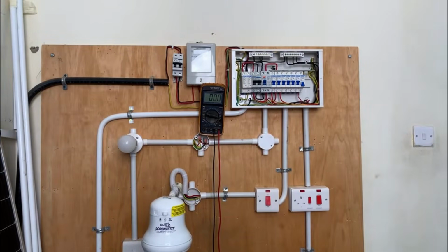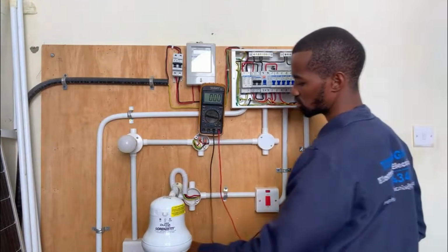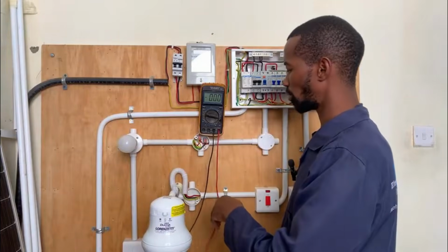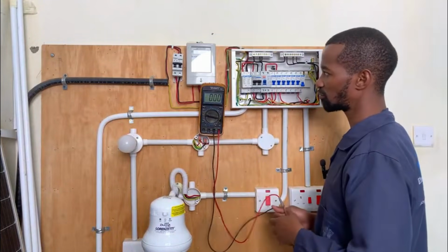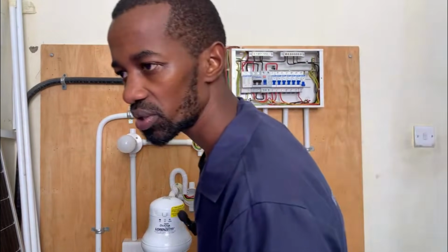I hope it was. This is my backup right here. Power is still out. So if this MCB has tripped, you isolate the circuit, you simply switch. Maybe there are several bulbs, lights, you switch them off. And then you take the readings for continuity. Continuity will demonstrate whether there is a short circuit.